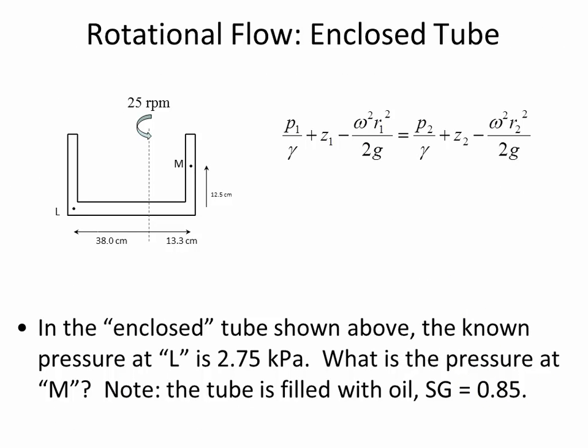Now the liquid is all the way in here, and it is filled with oil. So I give you the specific gravity of the fluid. But because there's a lid on the top, the liquid can't slosh around, but still the pressure changes. And the pressure increases in the opposite direction of acceleration.